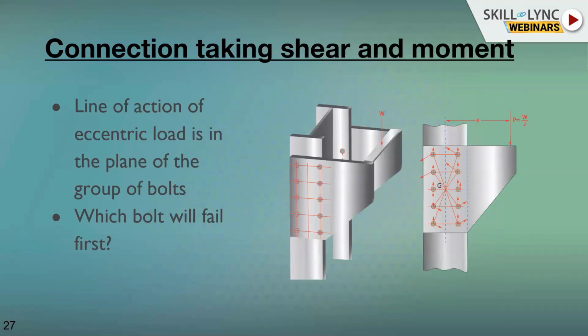Our steel connection is not limited to this, but we also have a load that has been applied eccentrically. The eccentricity of the load will also play a major role, because in natural load distribution, not every load is axial. Some eccentric load will also come. So if the load is eccentric, then every bolt will behave differently.